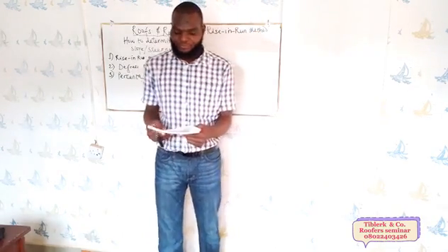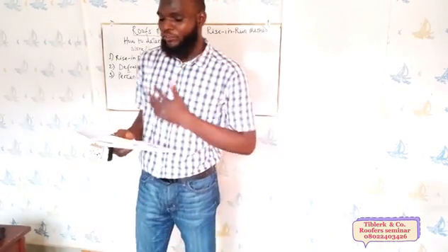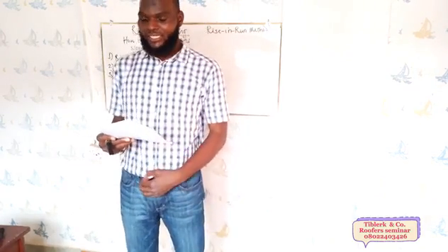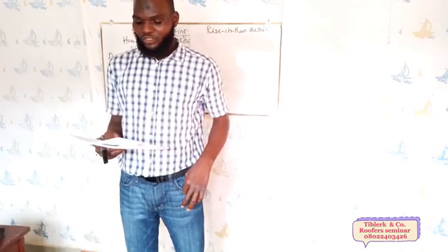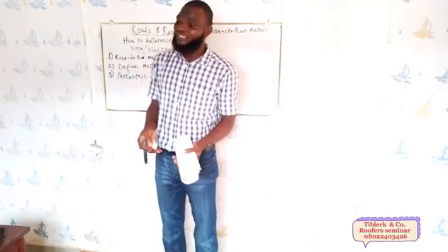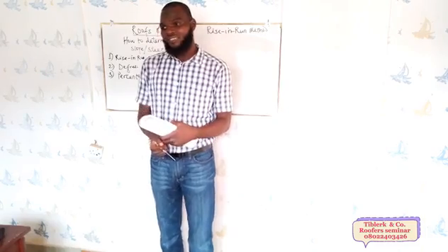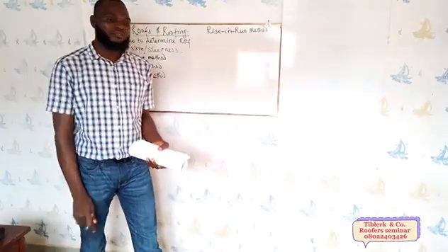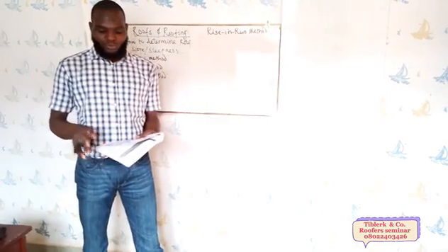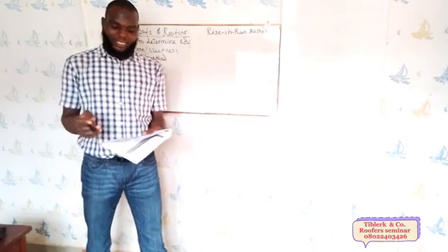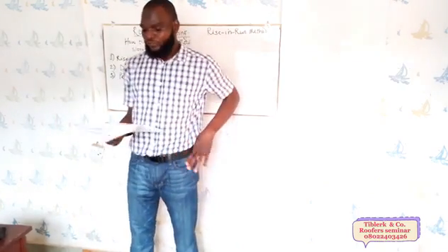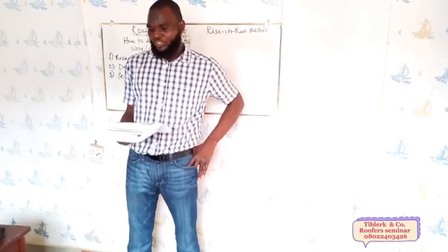In this method, the angle or pitch of a roof is calculated by the number of inches it rises vertically for every 12 inches it extends horizontally. When you are on site, this is what the carpenters, the artisans, use. It can be said, for instance, that the pitch of the roof is 6 in 12 pitch.